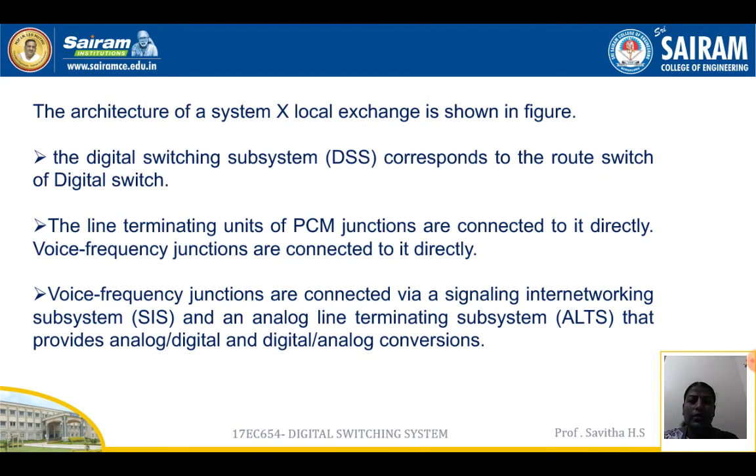The architecture of a System X local exchange is as shown in the figure. The digital switching subsystem corresponds to the root switch of a digital switch. The line terminating units of PCM junctions are connected to it directly. Voice frequency junctions are connected to it indirectly, via a signaling interworking subsystem and an analog line terminating subsystem that provides analog to digital and digital to analog conversions.